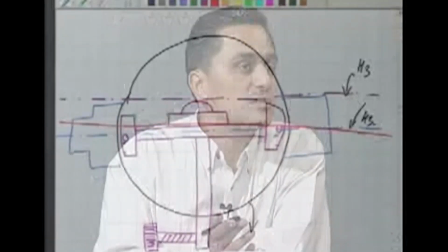So what will be the effect of this? The effect is very obvious. My face is left, the reading is 0, 0, altitude bubble is in center. I take the observation, the line of sight is going inclined, so I am measuring more angle. Next, I change the face, now the line of sight will go up.